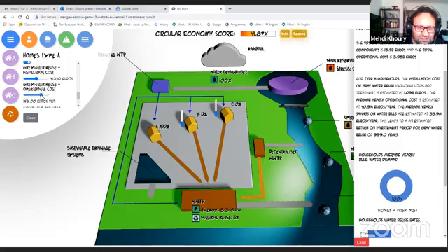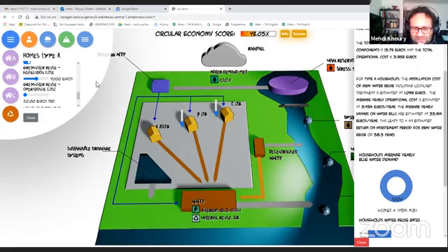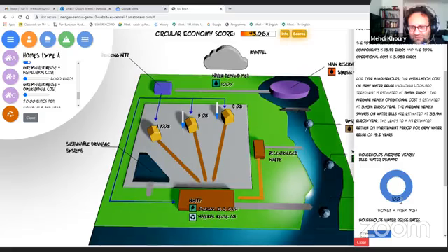So if I change my cost per year from 150 euros to 20 euros, then suddenly the return on investment period, instead of being 1,000 years, becomes 38 years. And if I was to change, because of an economy of scale, the installation cost from 4,000 euros to, let's say, 2,000 euros, then finally, gray water reuse can become practical and interesting from a financial point of view.